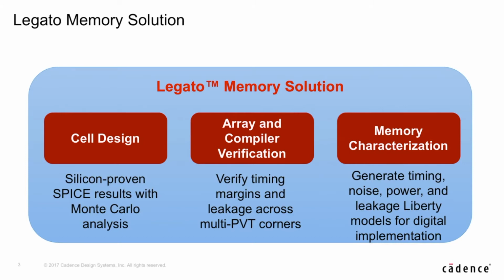So I talked about the meaning of Legato, and now you look at it. What Legato memory solution consists of is really 3 cockpits. We have the design cockpit, the verification cockpit, and the characterization cockpit. In the design cockpit, you use silicon-proven SPICE simulators, and you run Monte Carlo analysis to get the yield estimation. Usually in the design phase, you use it for bit cells or sense-amp.